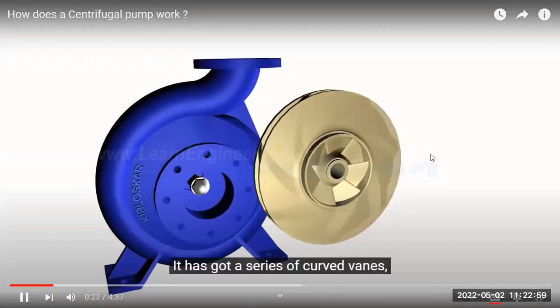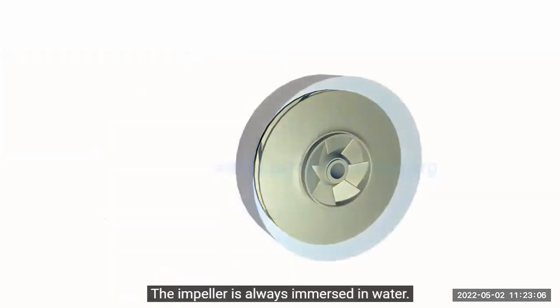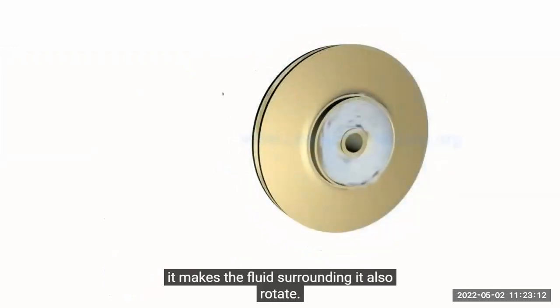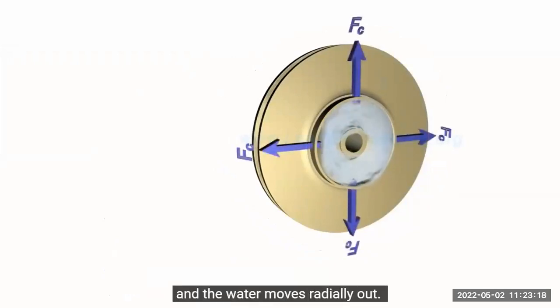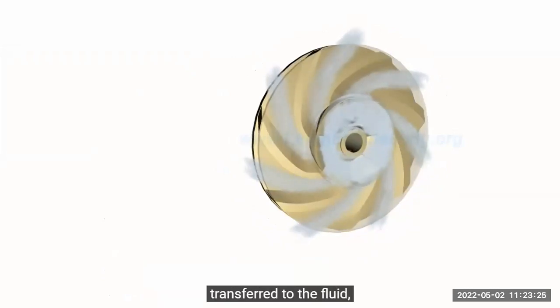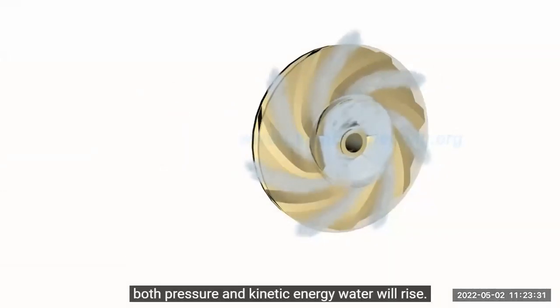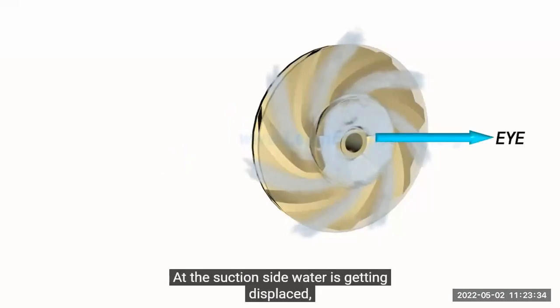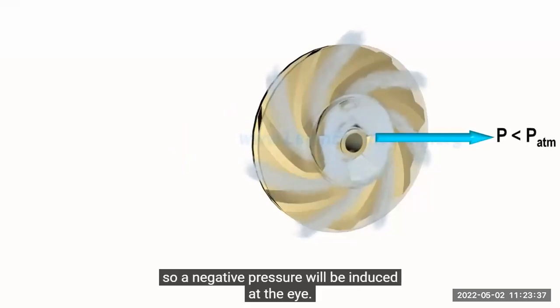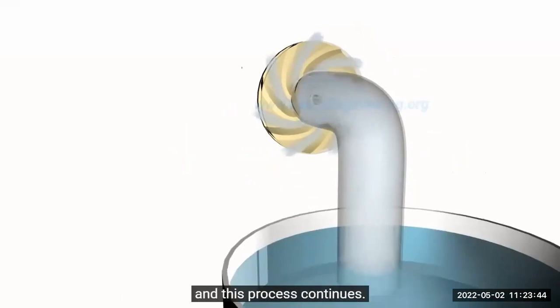It has got a series of curved vanes fitted inside shroud plates. The impeller is always immersed in water. When the impeller is made to rotate, it makes the fluid surrounding it also rotate. This imparts centrifugal force to water particles, and the water moves radially out. Since rotational mechanical energy is transferred to the fluid, at discharge sides of impeller, both pressure and kinetic energy of water will rise. At suction side, water is getting displaced, so a negative pressure will be induced at eye. Such low pressure helps in sucking fresh water stream into the system again, and this process continues.